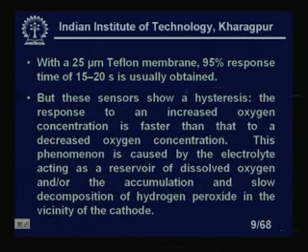But these sensors show a hysteresis: the response to an increased oxygen concentration is faster than the response to a decreased oxygen concentration. The response time varies depending on the direction of the step change. It is unusual for oxygen partial pressure to change very rapidly, but suppose there is a change.